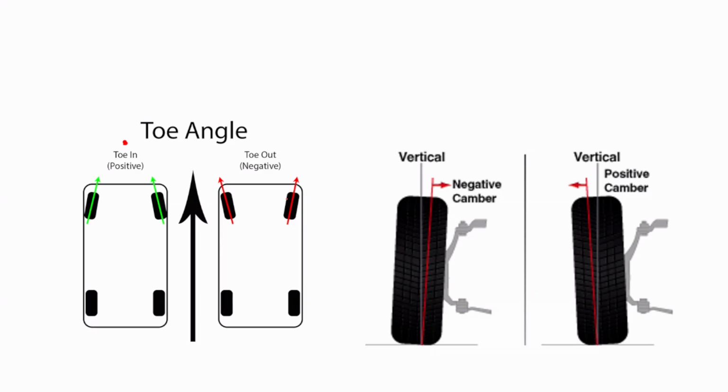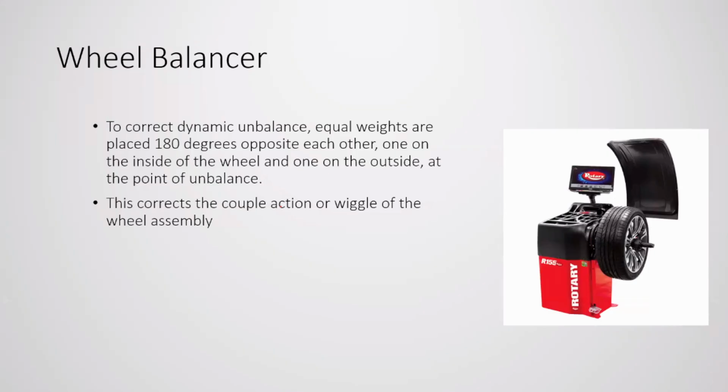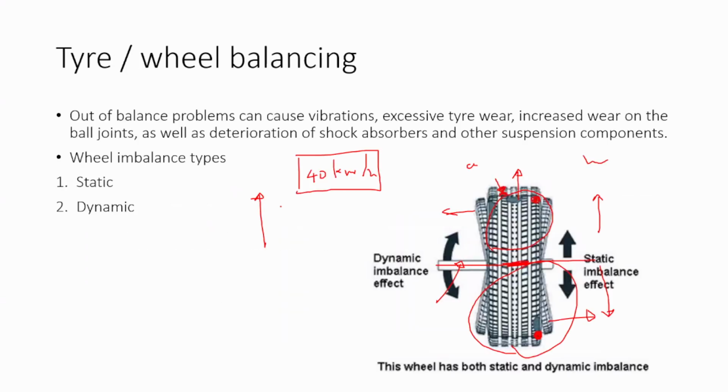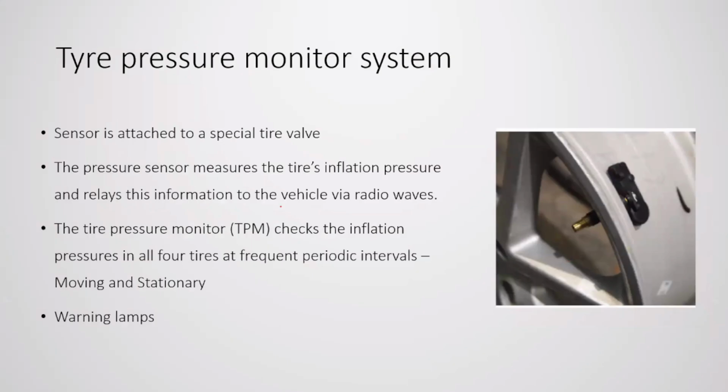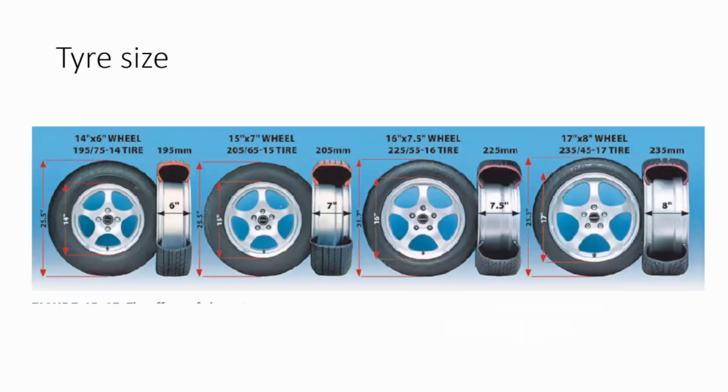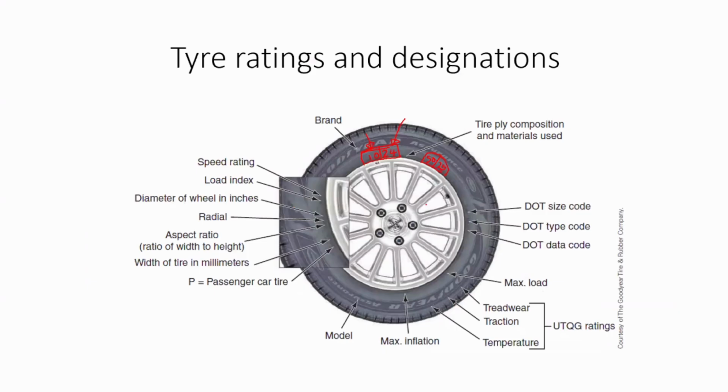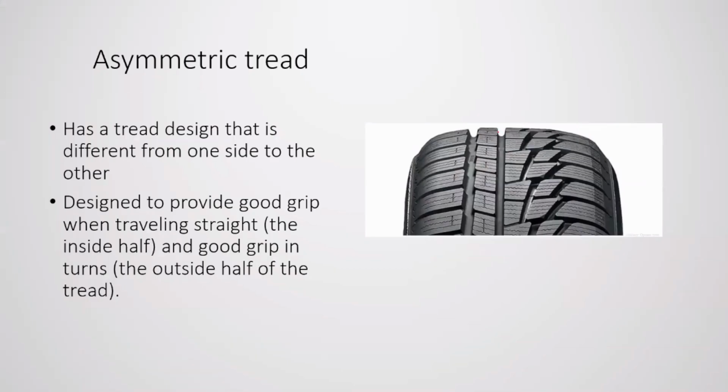There are some indicators in the tire. Can we see some indicator? Sorry, I forgot to include a tread wear indicator photo. Normally, tread wear indicators are located in tires. Let's say in our tire, in one place like this, there is a rib like this. Actually, not just one place, there are several places. So these are the tire wear indicators.